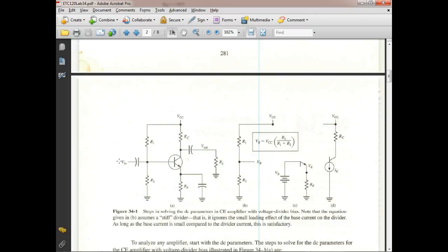And of course, it always boils down to what? Money. So when I filter it, with a full wave, since the pulses are occurring faster, it takes a smaller capacitor to get the output voltage. So with half wave, we have to use a bigger capacitor because it has to run the load longer. So a full wave unfiltered, that's the cheapest you can get. Then when you start adding capacitors, you say, okay, what do I need, right? How much money am I willing to spend? How good of voltage do I need?